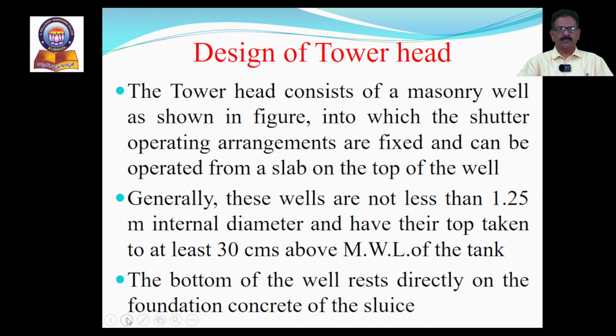Before discussing the tower head design, let us see why this tower head is required for any tank. Generally, sluices are the openings provided for a tank to supply water or to draw water from the tank. Without any regulating structure like this tower head, it is not convenient to supply water regularly and distribute it on time. Therefore it is necessary to provide some structure to regulate the flow through the sluice.